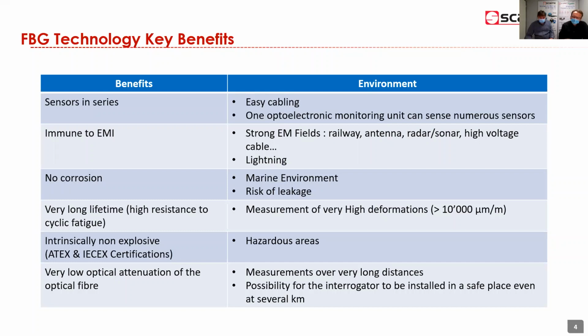And very important also is to say that we have ATEX and IECEx certifications for all our interrogators and sensors. This is a key point also. Very few people on the market are able to offer this. Yes, and this is very important because it's mandatory by law to have the certifications in these kinds of environments. Many people say it's only light, but if you have a very powerful laser injected into the sensors, then you have risks.